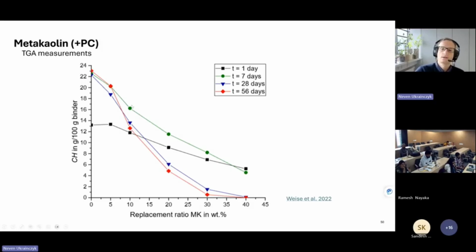This is the easiest way to determine the pozzolanic reaction in a realistic system, because you really have the Portland cement paste mixture with SCM, but I would recommend you to do the reference with the filler effect. Also 10% of sand, mixed with sand. And then you can really determine the degree of pozzolanic reactivity. Also with time for each of these, not only 56 days, you can determine for all the times.